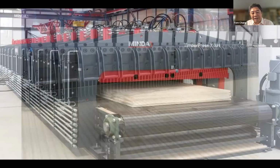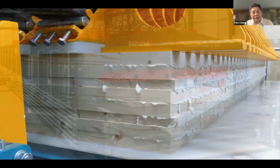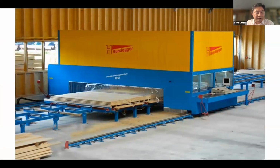And all of that is then fed into a giant press, where you can see here all of those laminates of wood are then glued together. It takes anywhere from about 30 to 40 minutes for that piece to be glued. And then that is picked up and brought to a different part, a post-production part of the facility, where all of that is shaped and cut using CNC technology.